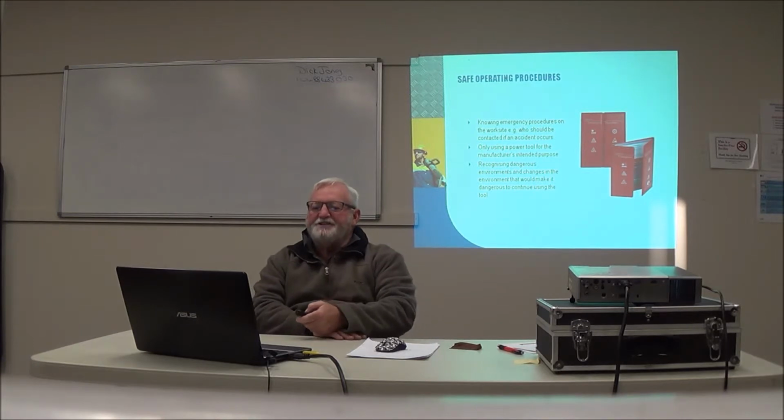Safe operating procedures. Knowing emergency procedures on a work site, for example, who should be contacted if an accident occurs. Only using power tools for the manufacturer's intended purpose, and recognising dangerous environmental changes that would make it dangerous to continue using that tool.